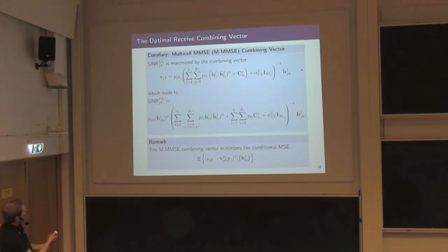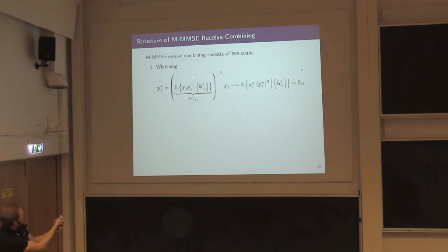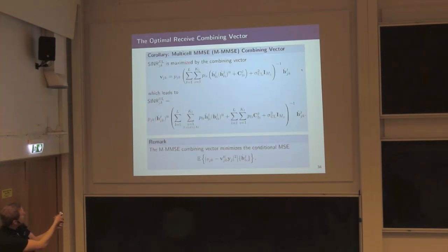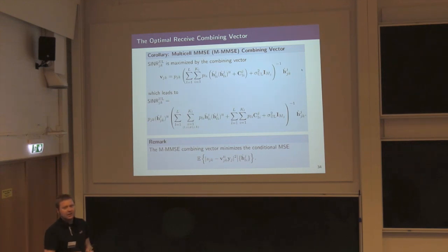Yes. So this part, this C_Y is actually this matrix here. And in this one, going back to the question, I include all the users, including myself. So it's both the signal and interference. You can actually take out the term here that contains my own desired signal. That will change the vector scaling, but it will not change the direction of it. And one can show this with the matrix inversion lemma, that one can take out one of the terms that will only create a scaling of this vector.